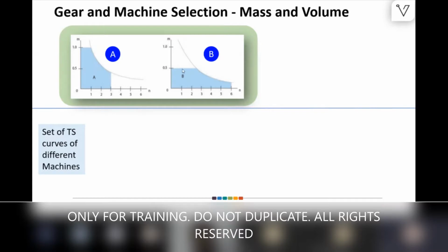We can take this machine and amplify the torque for the peak operations. So gearing also comes into the picture when we look at which machine we are selecting. At the back of the mind, the system integrator has to keep referring to the gearing to check that it is feasible.